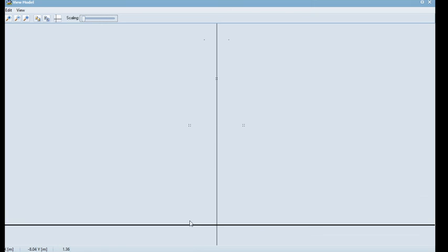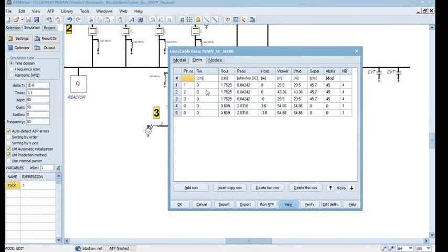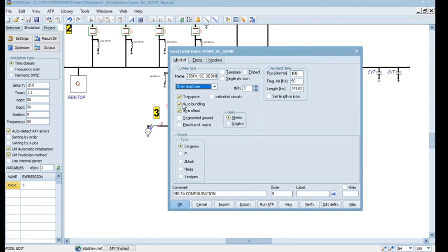But here you have a ground plane, and in the center you have the R phase, Y phase, and B phase with 4 conductors and 2 ground lines, right? Which corresponds to this setting. So ground lines you always specify with 0, and 1 phase, 2 phase, 3 phase. When you see the bundling, it is already connected, and you can name something, and when you say OK, it will create a small file which you require to run it.